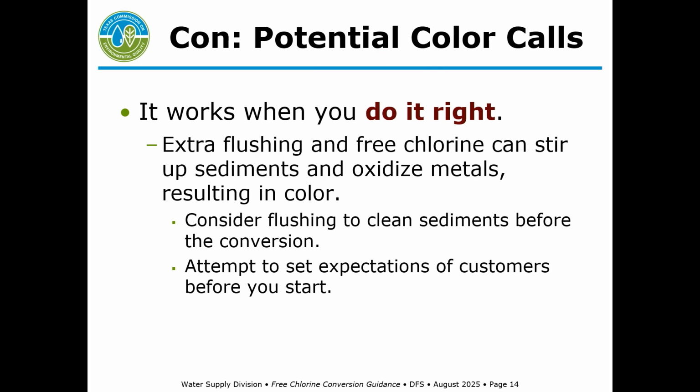You can also have color issues. This is particularly at PWSs that have iron and manganese issues, and they decide that they don't want to flush regularly because it stirs up the sediment, so they're just building up sediments in the distribution system. That practice of not flushing because of the color can actually promote nitrification. The nitrifying bacteria can live in those sediments.